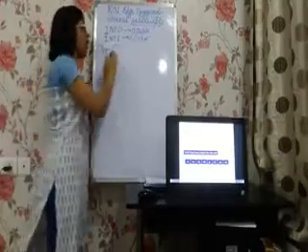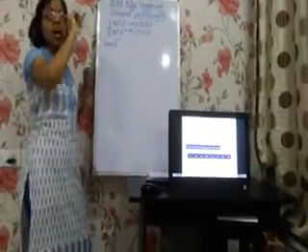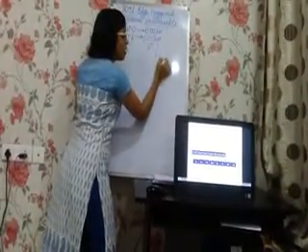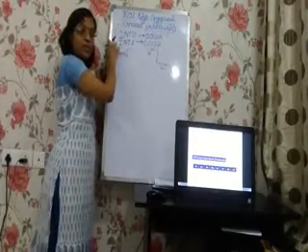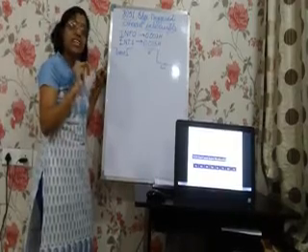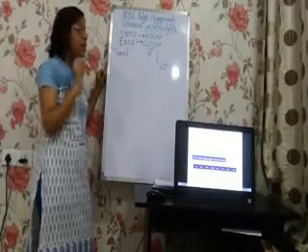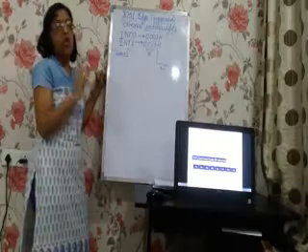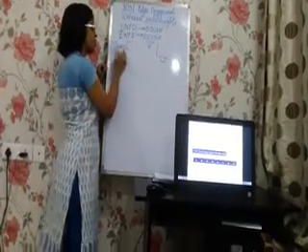Now if we want to use them as edge triggered, what does edge mean? When a high to low transition is obtained on any of these pins by connecting an external device which gives the signal, the interrupts get defined as edge triggered interrupts. Now how do we define the interrupts as edge triggered interrupts? For this, we have to configure the TCON register.